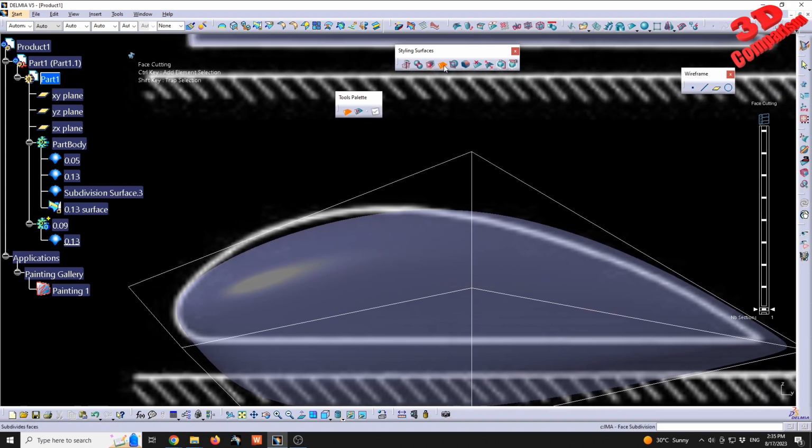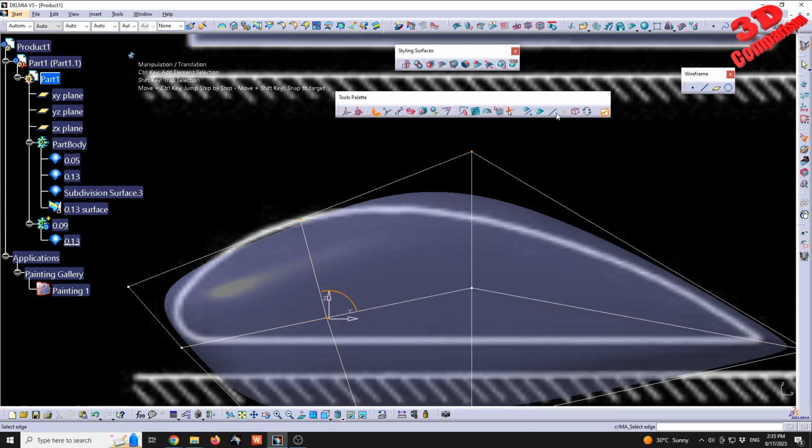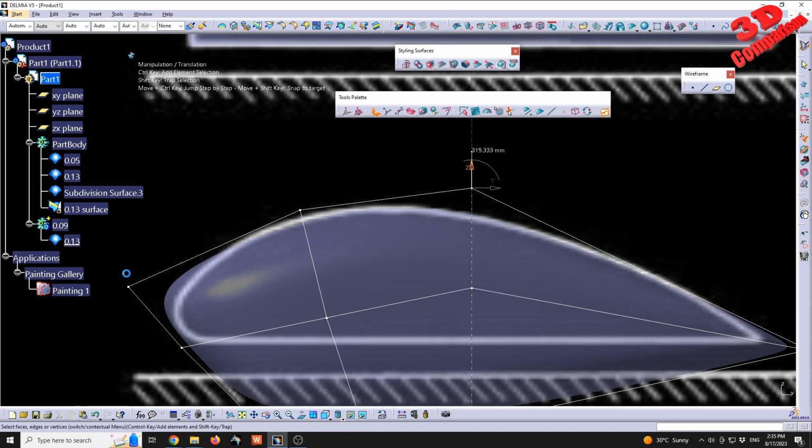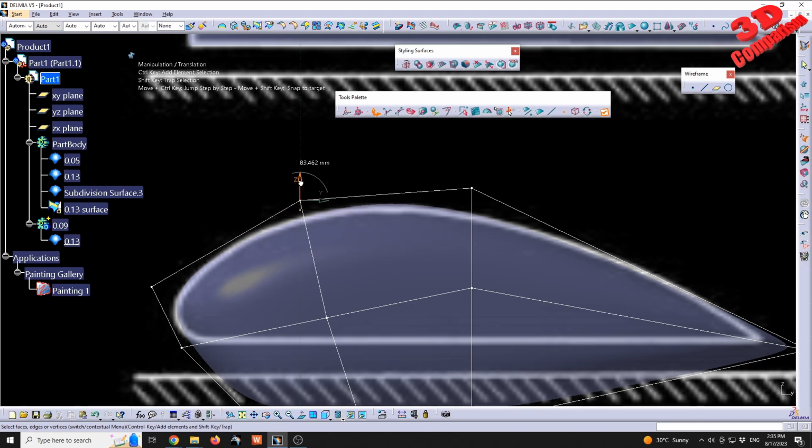curvature. So again, go with face cut and do one additional cut over there. But keep in mind that each additional cut that you create will bring you a little bit closer to the intended, let's say, design shape, but that cut also moved what I already centered, so I will need to reframe that. This is why imagining shape requires more time. It's not as, let's say, exact as part design, where you can just specify the value and you're going to have that, but it offers a lot of flexibility, because if you would want to model this within part design,